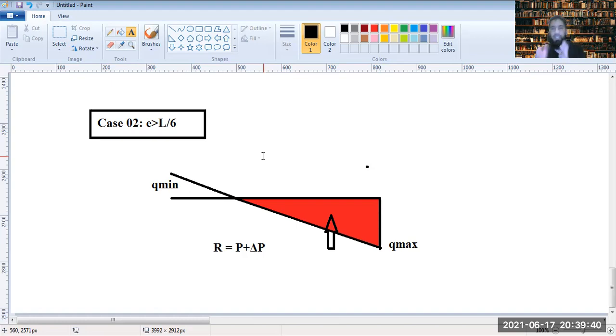Because now the contact area is less, more pressure will come on the soil. And that soil pressure has to be taken up by the part of the soil which is in contact with the part of the footing. So it depends naturally on the amount of eccentricity. The greater the moments, the lesser the contact between the soil and the footing, so the less effective the footing actually becomes.